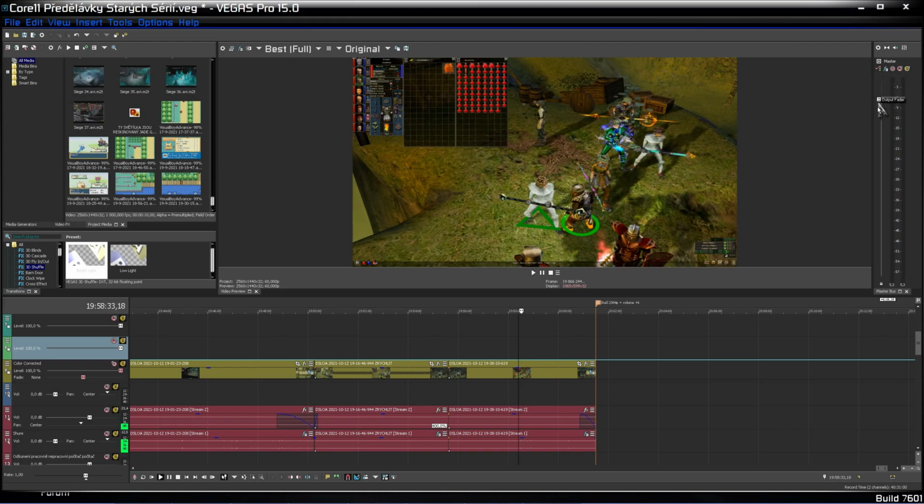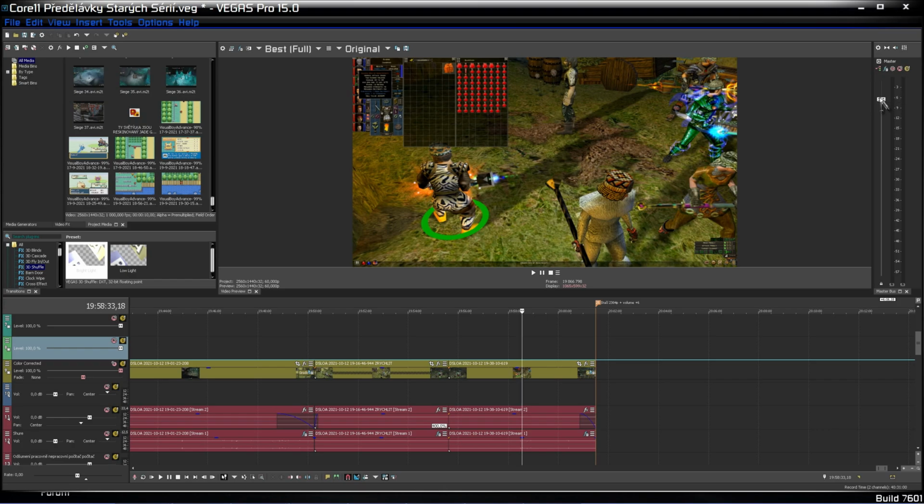I have this set quite low here, which means it will try to move whatever is lower up to this value a bit, and the other way around. If it's something that's higher, it will start to roll it down. If you go beyond a certain threshold, which will be shown in red, it will start to clip the peaks of the audio, seriously damaging the audio pretty much without a way to fix that. So you don't want to have audio that's too loud, that goes to, I don't know, a resonance frequency, and that's just bad juju.